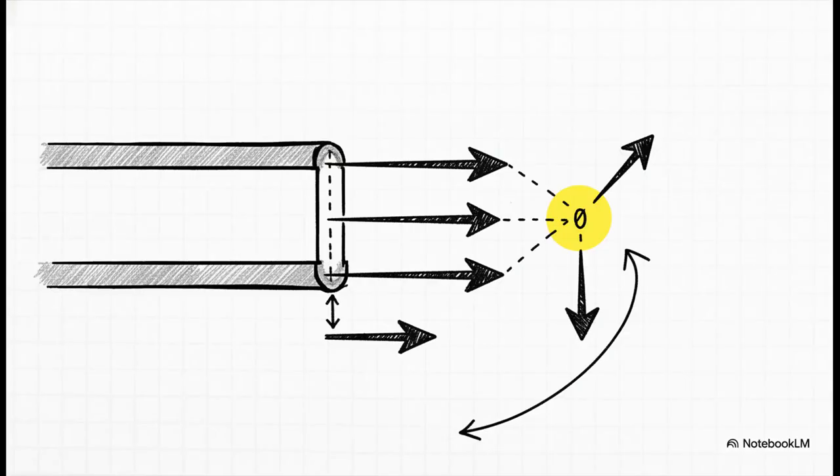So here's how the magic trick works. You make an imaginary cut right through the truss, slicing through the piece you care about. Then, you use our old friend, the moment. By cleverly picking a pivot point where two of the unknown forces meet, their rotational effect on that point becomes zero. They have no leverage, so they literally vanish from the equation, leaving you with one simple calculation that solves for the third and most important force. It's just an elegant and incredibly powerful way to solve a complex problem.